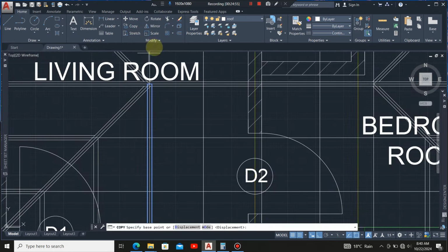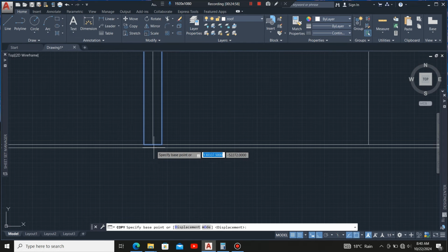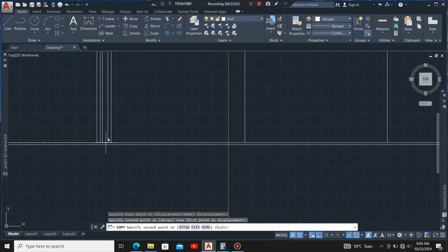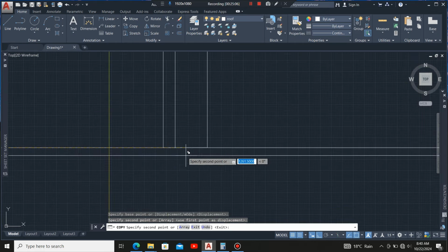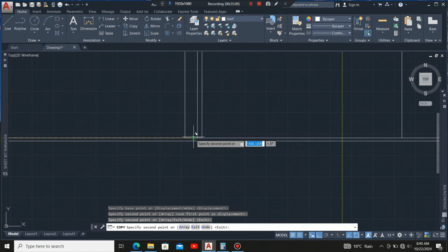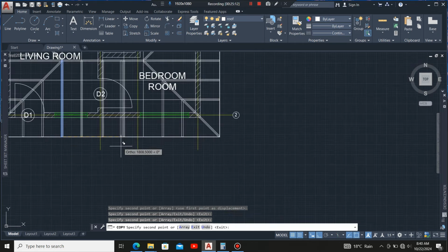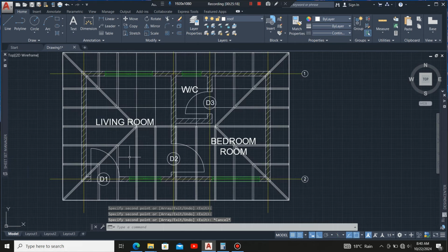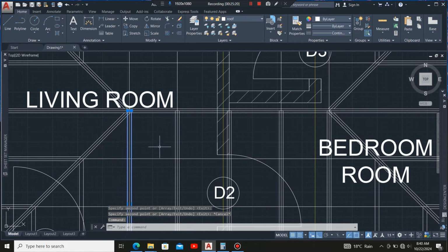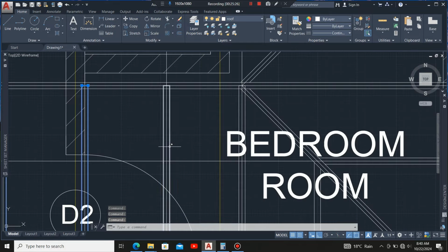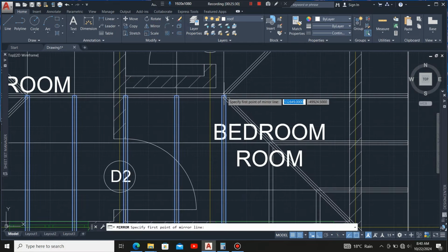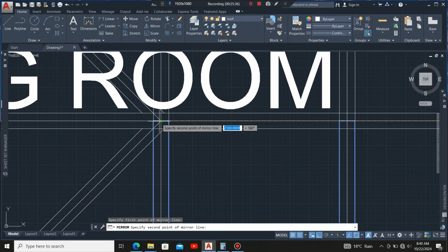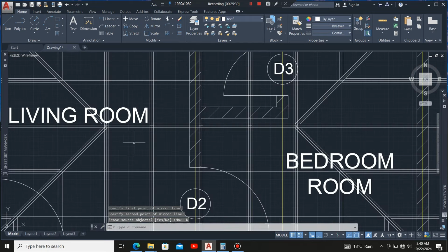Then I'll click at the move command and I'll move it up to this point right here. Still I'll click at it, then I'll stretch it out up to that point. Then I'll click at the copy command. Then at this point, I'll copy that common rafter to these different points. Lastly, at this point. So I'll highlight them. Then I'll just mirror them to this other side of the roof. Then I'll hit no.